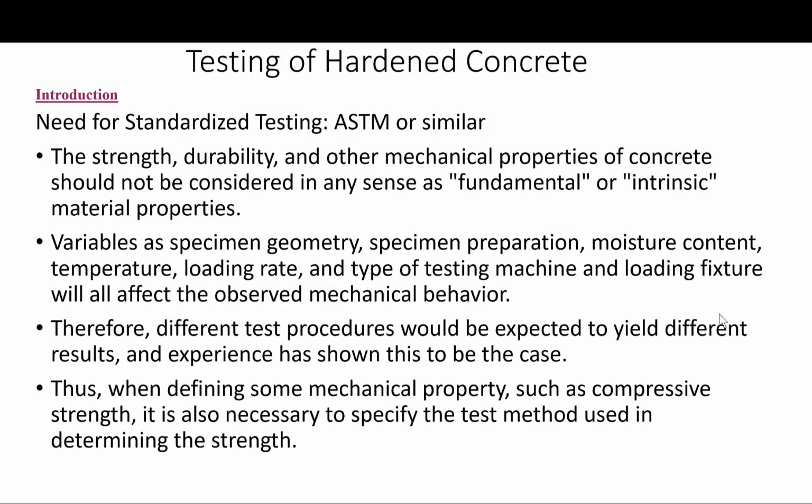Okay, the strength, durability, and other mechanical properties of concrete should not be considered in any sense as fundamental or intrinsic materials properties. Such variables as the specimen geometry, specimen preparation, moisture content, temperature, loading rate, and the type of testing machine and loading fixture will all affect the observed mechanical behavior.